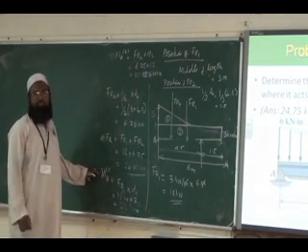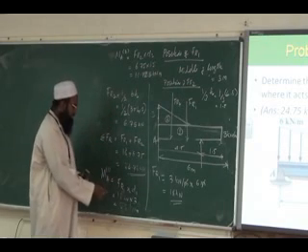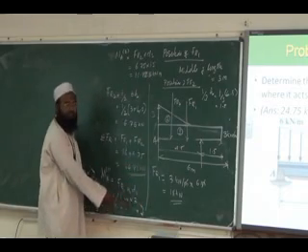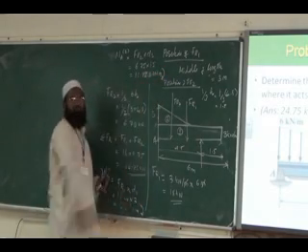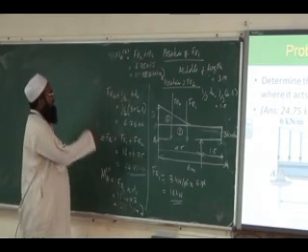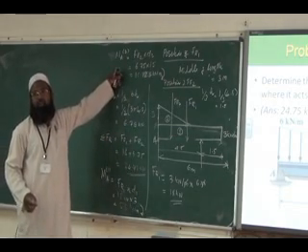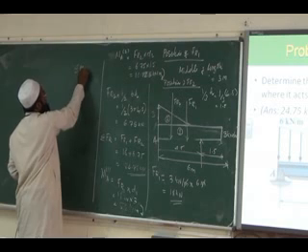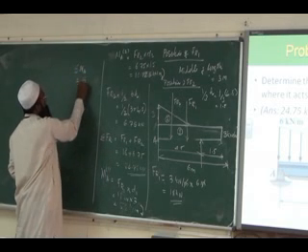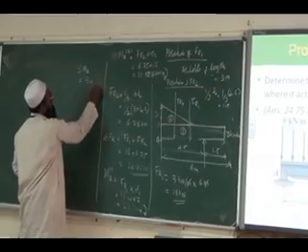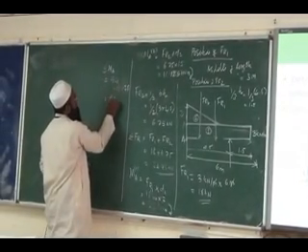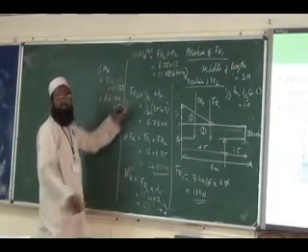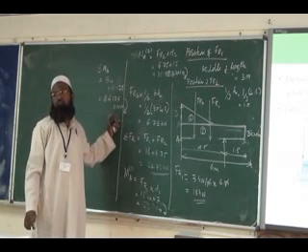According to the sense, they have a clockwise rotation, so we can write 54 kilonewton meter clockwise. This also is clockwise, or you can take it as negative. After that, you add them up to find the resultant moment. Sigma M about A will be 54 plus 10.125, so 64.125 kilonewton meter clockwise. Both are in the same direction. So this is our resultant moment.